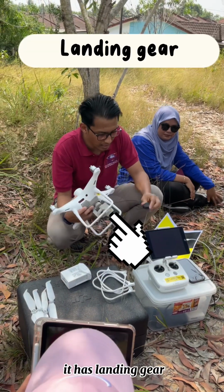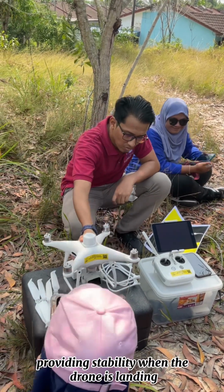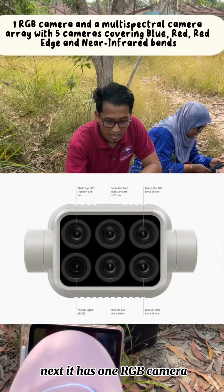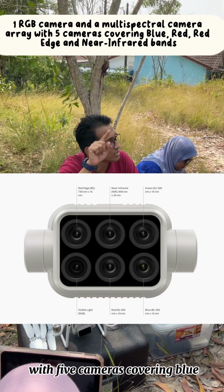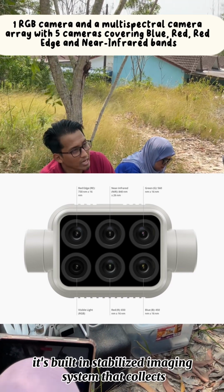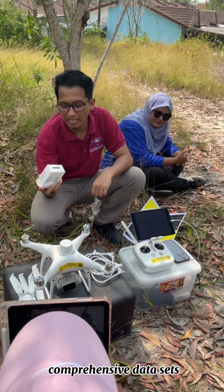It has landing gear. Landing gear can absorb shocks and vibration, providing stability when the drone is landing, taking off, and in flight. Next, it has one RGB camera and a multispectral camera array with 5 cameras covering blue, green, red, red edge, and near-infrared bands. Its built-in stabilized imaging system collects comprehensive data sets.